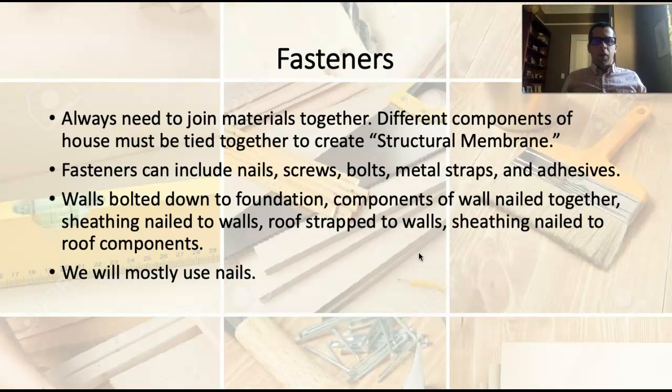But when we think about that load transfer, the weight of the roof is primarily what we're trying to mitigate. The house is very top heavy. We want the weight of that roof to travel through the studs, through the framing, down to the foundation. And then we want all of those components to be attached together. Because banging a couple nails through something isn't enough to hold it together if there's 120-mile-an-hour winds blowing on it or an 8.0 earthquake trying to rip it apart.